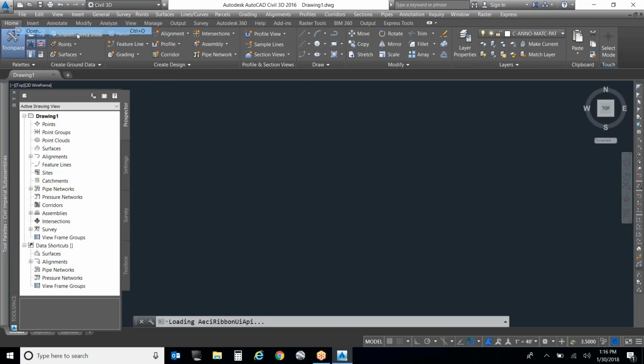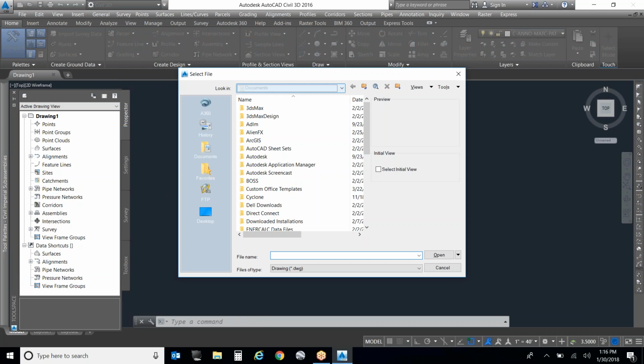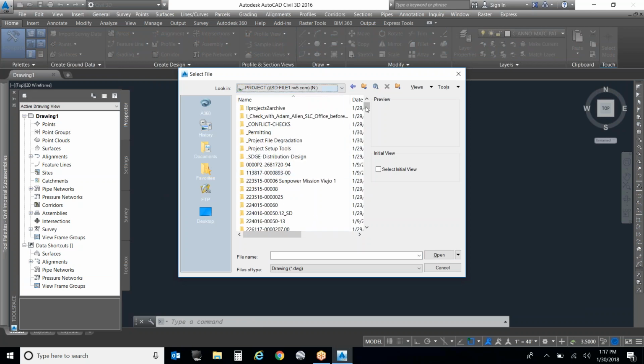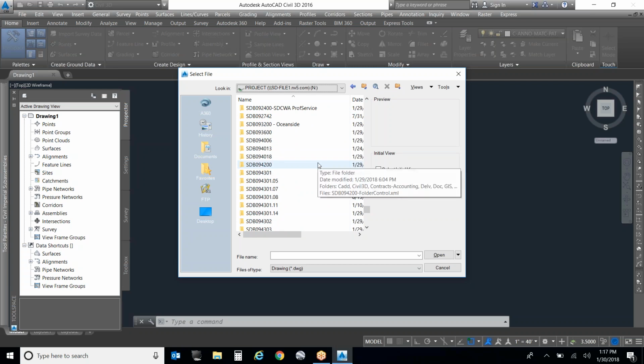and then you have your survey. Okay, you have your survey, and you told survey that you want cross sections at 25 feet. Okay, and you have that surface built basically good to the back of walk, or the back of parkway, and so that's your detailed surface. You cut out of the aerial plus or minus 3 to 5 feet beyond that back of walk. Okay, so you just take the back of walk and then cut it, and then paste in that aerial surface.